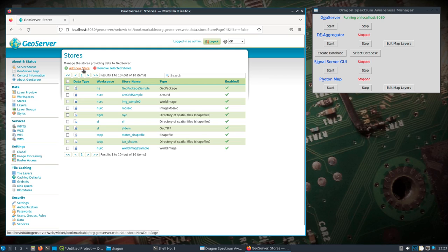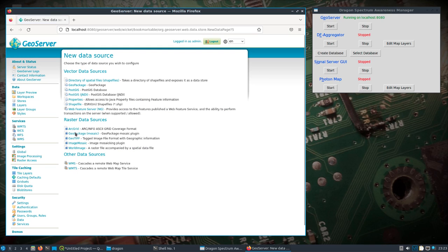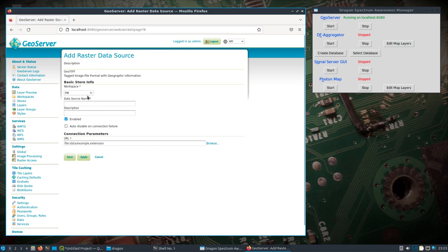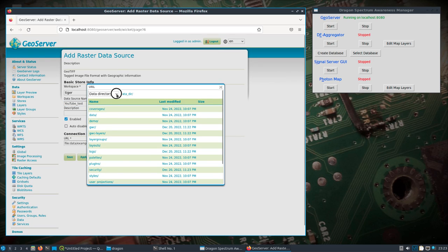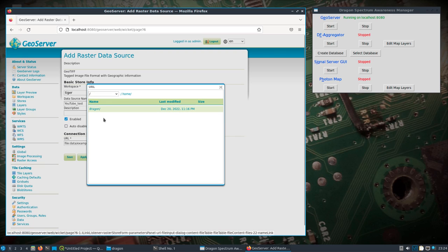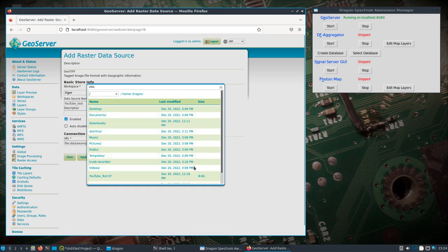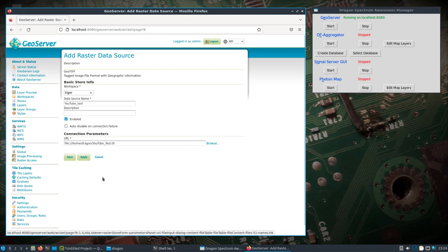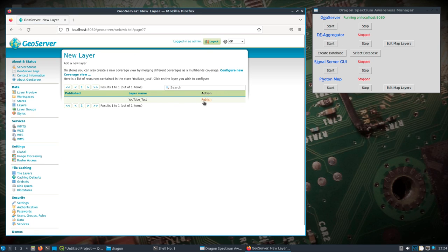I'm going to add a new store. We talked about this before. Go to GeoTIFF. I'm going to put it under the Tiger workspace, and we'll just call this YouTube test. And we need to browse for it, so we'll go here, and we go home, Dragon, that 8 gig file. We'll save and publish this.